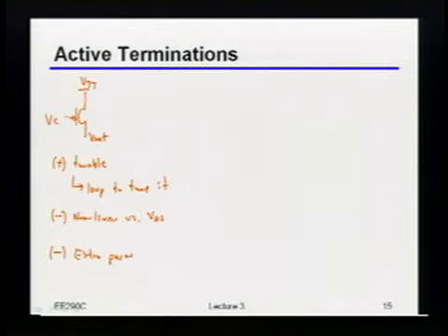Right? Because basically for the same sort of unit resistance that I could have gotten from that poly resistor, I'm going to get a lot more cap from this structure. Yeah? Probably pretty sensitive to ESD. Okay, so that's right. It is actually not the most ESD robust. Right? So I actually have to be pretty careful to make sure that this thing won't blow up, instead of just something else, because, hey, this looks a heck of a lot like my active circuits. Right? So that's actually also absolutely correct.